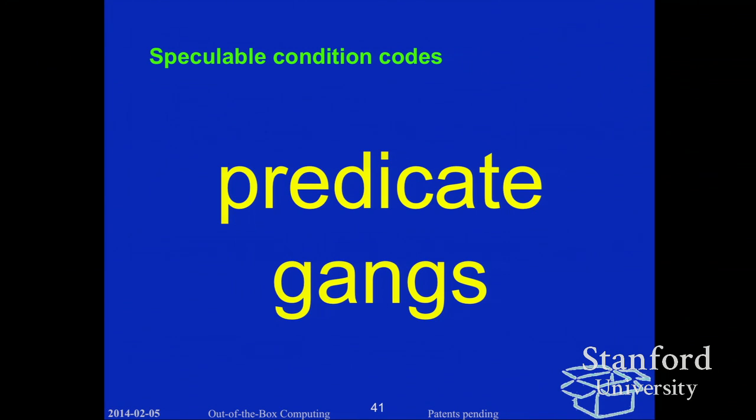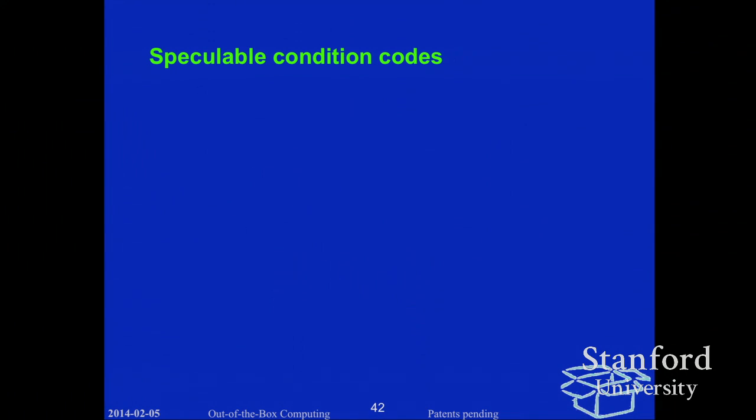All of the people who actually have to do things like modern x86 chips do dearly wish the condition codes had gotten left out of the original architecture, but the original architecture did not have that much of a view of the future. On the other hand, condition codes will speed up some kinds of code, but they can't be speculated because it's a global state.